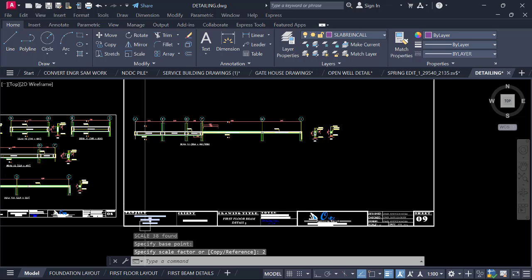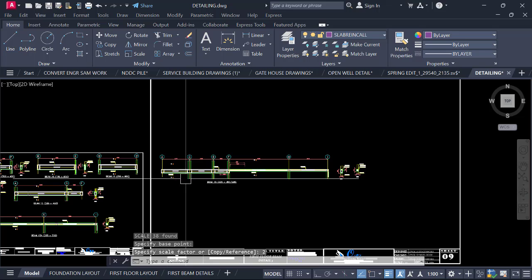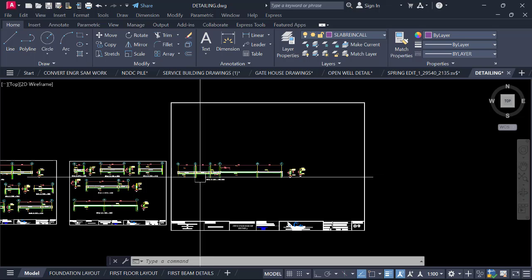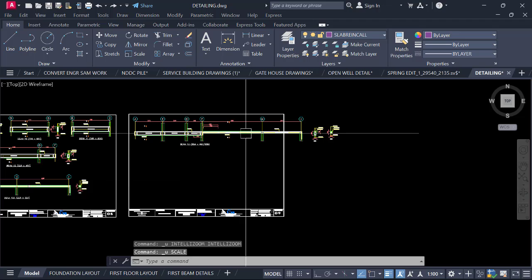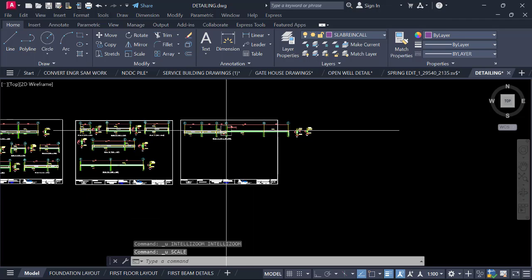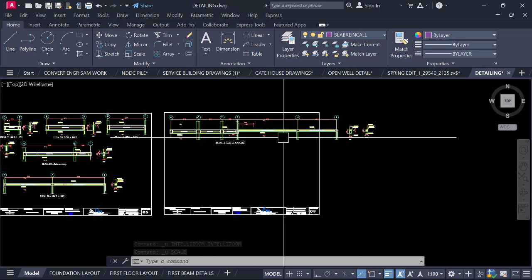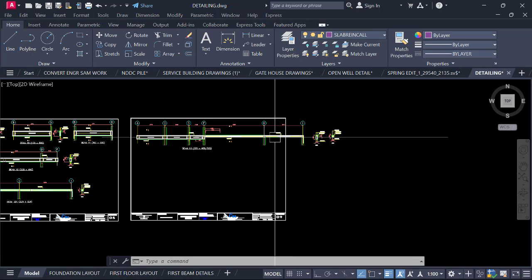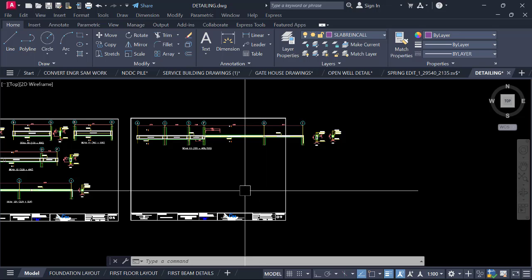Okay, you can't scale like this just because you want to put in your drawing. Once you do this, your structural drawing printout will not appear well. Stonebridge requires that you do not scale the sheet. So I've just done undo now and then brought it back. When you have this kind of thing, make sure you don't scale up your sheet. You will have issues on that.